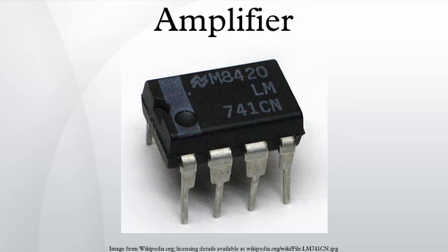Compared to an equivalent Class AB device, a Class D amplifier's lower losses permit the use of a smaller heatsink for the MOSFETs while also reducing the amount of input power required, allowing for a lower capacity power supply design. Therefore, Class D amplifiers are typically smaller than an equivalent Class AB amplifier.